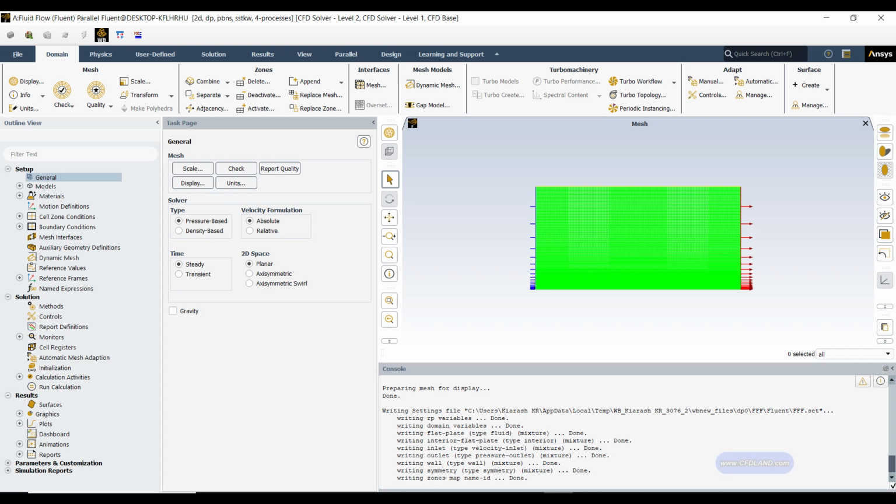In the pressure-based solver, we are assuming incompressible fluid or low speed flows in which the Mach number is usually less than 0.3. So in these cases, we can assume that the density change is negligible, and we can avoid the change in density. But for cases with high speed flows or where compressible flows are actually included, we cannot neglect the density changes.